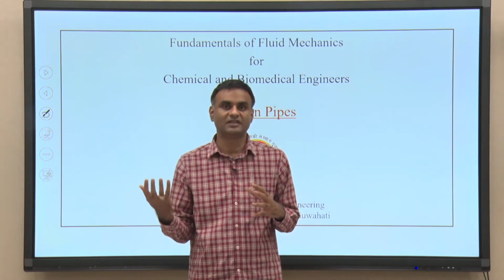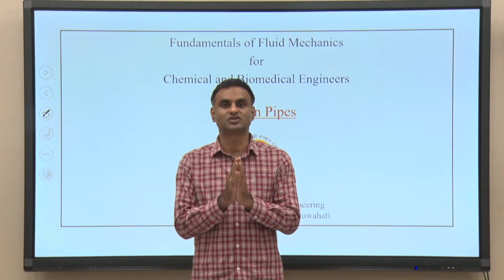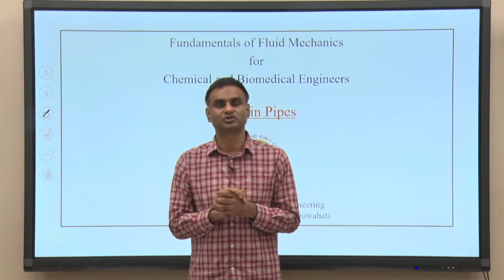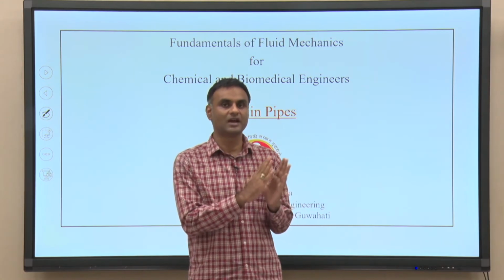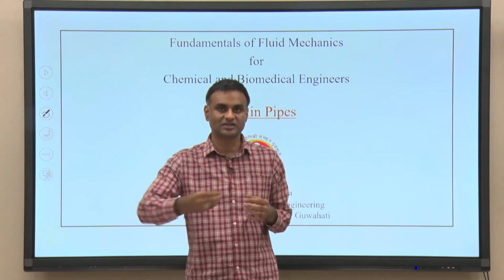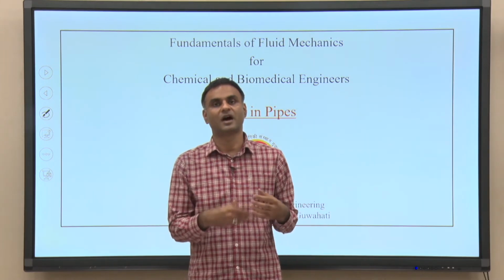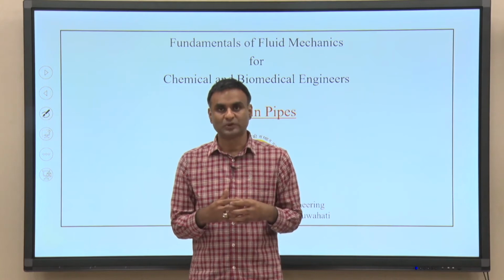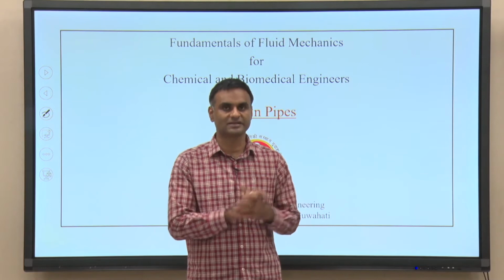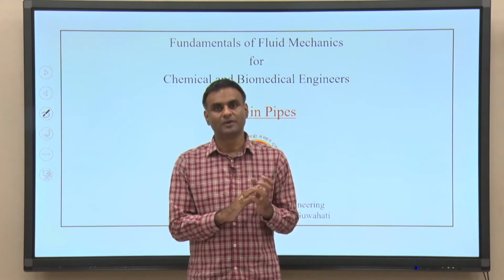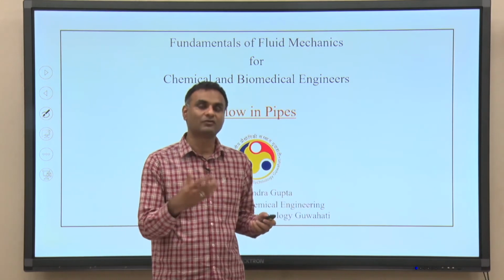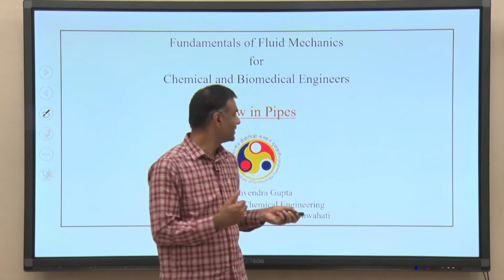When you need to design the pumping system, you need to know how much pumping power or how much head the pump should be able to provide. When I say head, I mean how much pressure the pump should be able to provide, so that the losses that happen in the system are overcome. That is a very important calculation, and the focus in this module will be on such things, especially the calculation of head loss in the pipes.